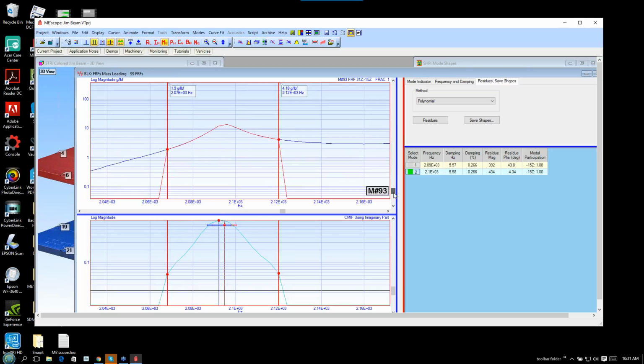So now what do we do when we save the mode shape away? Well, there's where we average all these local values of frequency and damping together. Now, are they a whole lot different than the global estimate? Well, yeah, some of them are. You can look at the values here as I drop the cursor, but you can see that they do change with each measurement.